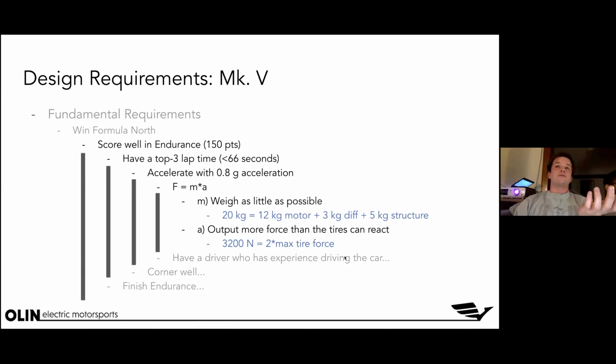Where this number comes from is we did some simple analysis and looked at our specific type of tires and found that the maximum amount of force that one tire could impart was 1,600 newtons under the ideal acceleration case. And so we decided to size our transmission system such that it could apply 3,200 newtons, or greater than 3,200 newtons, to the road, meaning that the transmission is not the limiting factor on acceleration, the tires are, which, as Nate said last week, is the way that things should be designed, such that none of the other subsystems reduce the effectiveness of each other, the vehicle.